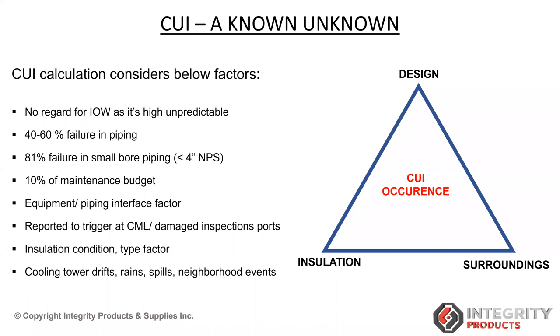So I would like to throw some light quickly on the concept of integrity operating windows within the asset integrity program. It's like having an old-fashioned car: we will try to run it at lower speed, and we won't try to use it for traveling to remote locations. In the same way, depending on the damage mechanism in the process equipment, we lower down the operating conditions to avoid any sort of failure in the equipment. So that is the concept of IOW.